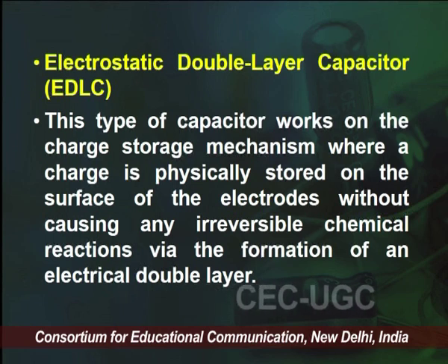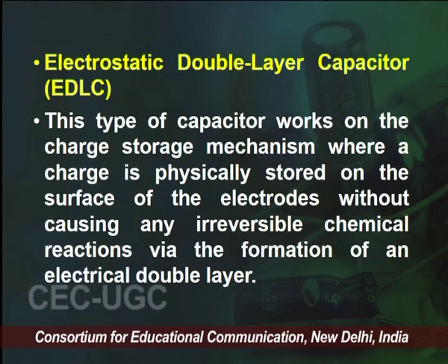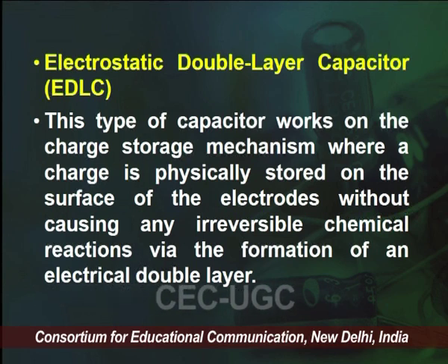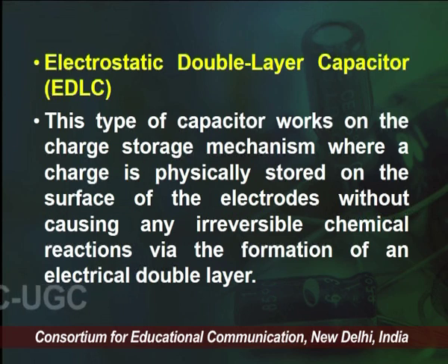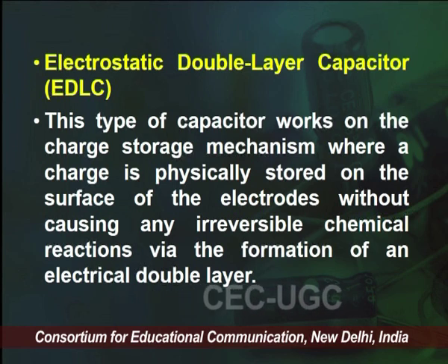This type of capacitor works on a charge storage mechanism where charge is physically stored on the surface of the electrode without causing any irreversible chemical reaction, by the formation of an electrical double layer.